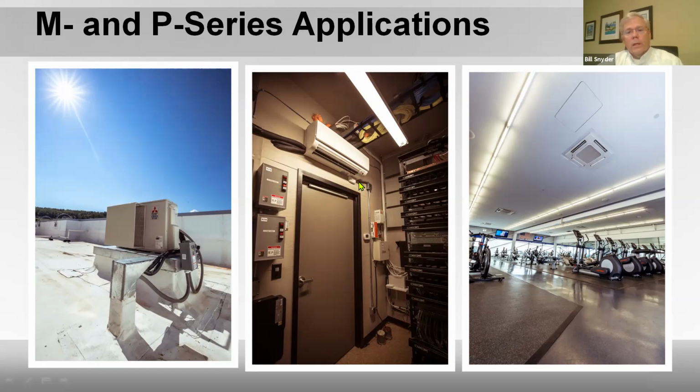They've got the condensate, it looks like running probably out there. That's where your line set is running. It looks like this is just electrical on this side. So electricity went in this side. It looks like the condensate and all runs out this side. I am guessing they insulated the condensate because the condensate will be cold and could drip. And they don't want any dripping in this room at all.